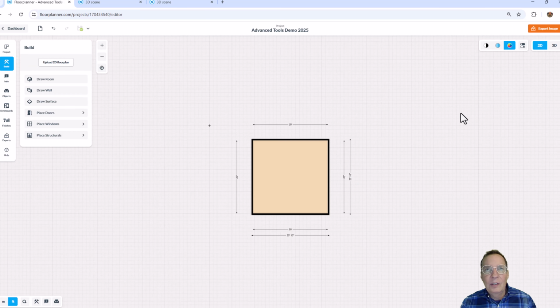Now we have a flat ceiling, automated, yes. Always remember that these automated flat ceilings are being created, or any ceiling is being created, based on the wall heights. So your wall heights need to be uniform. They need to be the same height, so you don't have any confusion. If you ever have any white triangles coming down from the ceiling, odds are you have some small little pony walls or small little height walls that are connected to your structure, and your ceiling is trying desperately to connect to them. So that could cause a little challenge.